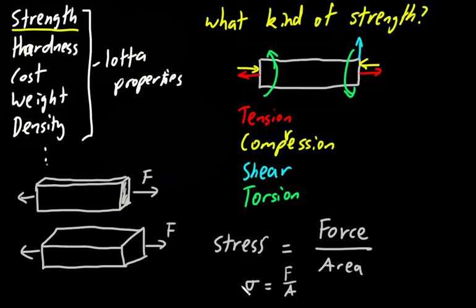So the units for this, I'll give a different color. Let's get blue. So this is given in pascals. Generally, because materials are pretty strong, you generally have mega or gigapascals. The force is generally given in newtons, and for the area, generally you want to go with meters squared, but often we deal in millimeters, so you just convert into meters squared, or you'll have different tricks that we deal with later on. With that, I'll finish up.